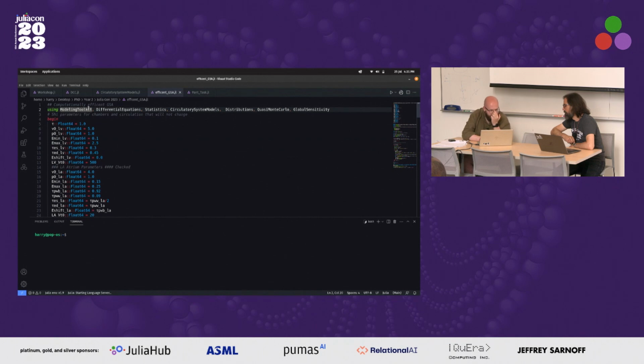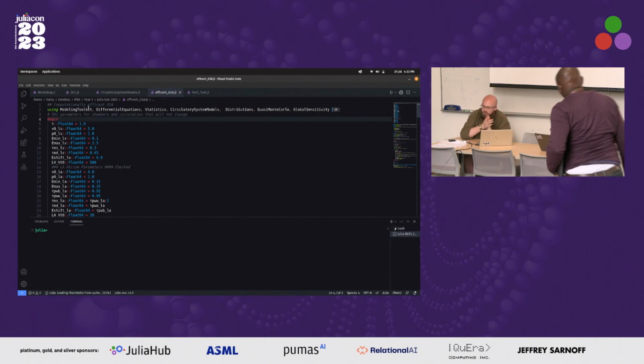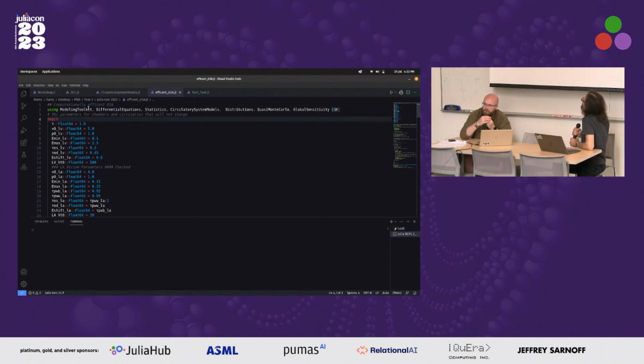So, should we go through this global sensitivity analysis? Because I think one of the big drawbacks that this acausal modelling front has is that when you do that structural simplify, it obviously eliminates the variables and returns the ones that are kind of the easiest to solve. But then to perform sensitivity analysis, you'd be very lucky if your solution vector, which would be the states, are the ones that you're interested in.